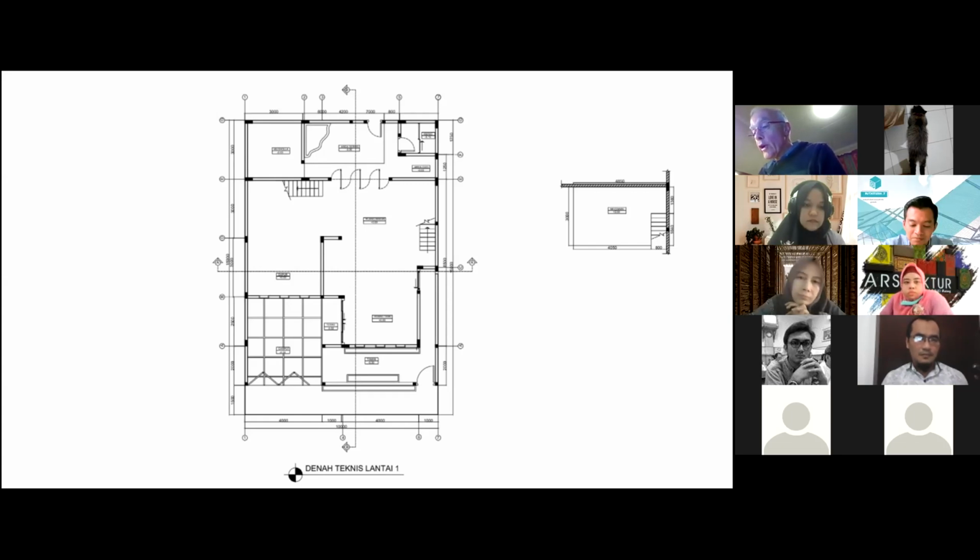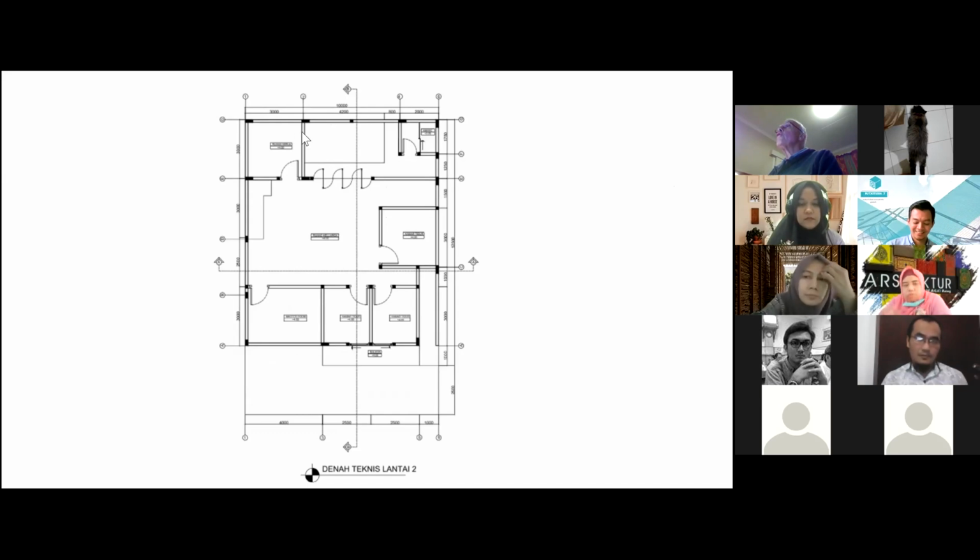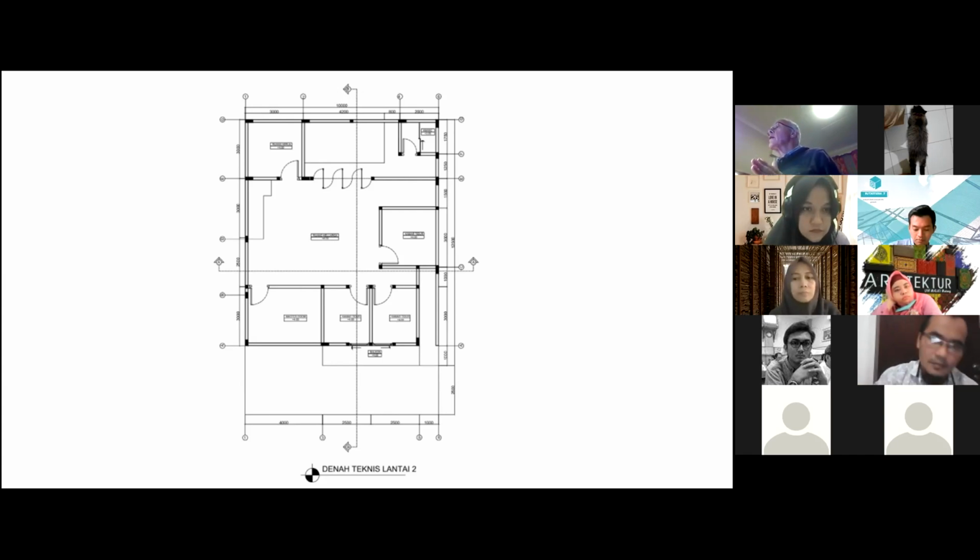And I could also mention to you that there are also some shorter walls on grids 2 and 6 here, because these two walls, if we look at Lantai Dua, you see the wall continues to the roof on grid 2, and also on grid 6, this wall continues to the roof. And so those two shorter walls can also help resist earthquake in the y direction. But actually, I don't think we need them because the walls on grids 1 and 7, on grids 1 and 6, are so strong.